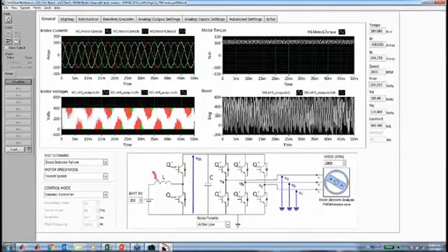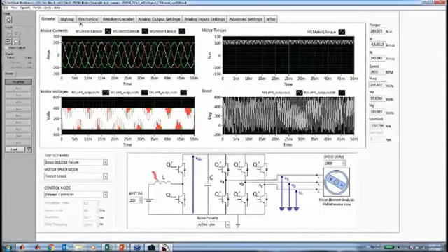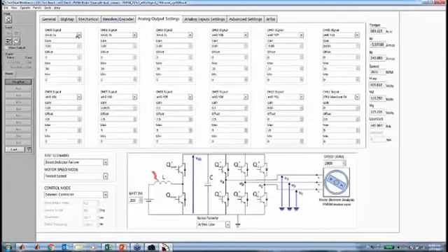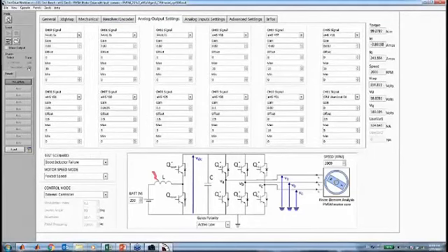Obviously, it's not the only feature we have with DHS. We have plenty of other ones. For example, it comes with a tool that helps you map all your analog outputs to your interface. You can apply mean, max value, saturation value. If your controller doesn't support 16 volts, you can put it to 5 volts. It comes with gain, offset, all the settings you need.